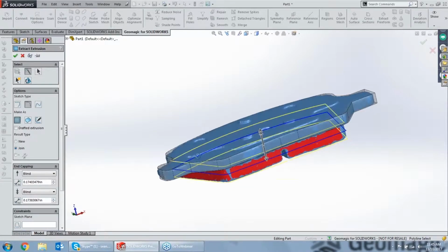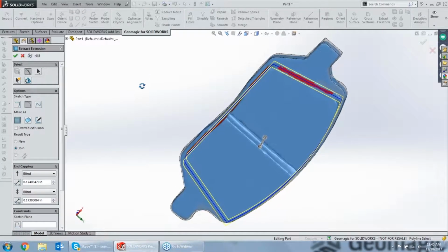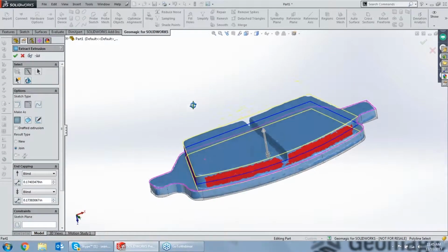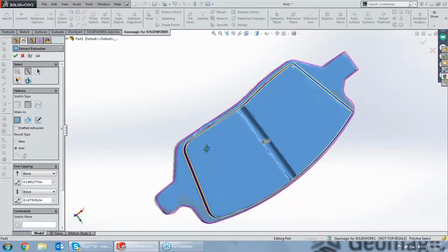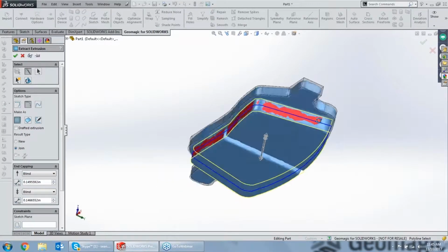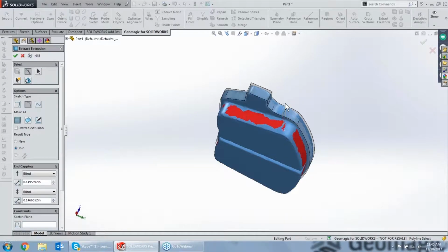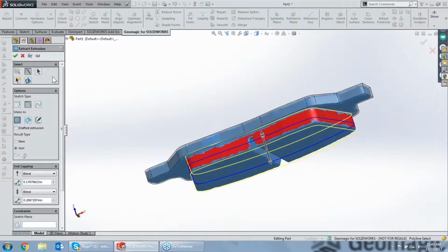And I'm not doing a bang up job of selecting all these radius corners here, but it does allow me to optimize this profile, and it will find more of those radius areas here, or I can go back in and manually select them. Or of course I could just model those radii as fillets later on, rather than trying to incorporate them into my sketch profile.